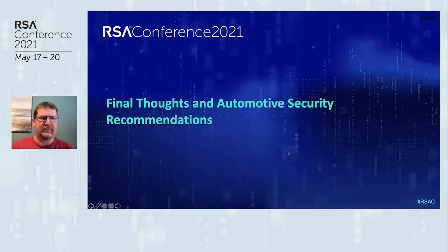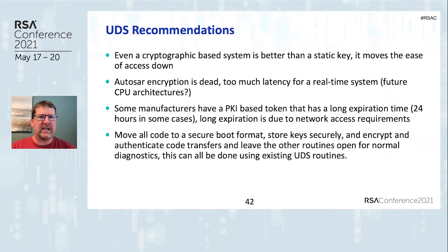So when we get to the final thoughts, some recommendations that we made. I actually was able to consult with a friend of mine, also head of the Car Hacking Village, Rob Leal from CAN Bus Hack. He provided some good recommendations that I'll be going through in these steps. But the biggest thing is do something other than a static key. Don't use a static key for that security access. Even a simple cryptographic system that moves the ease of access down.